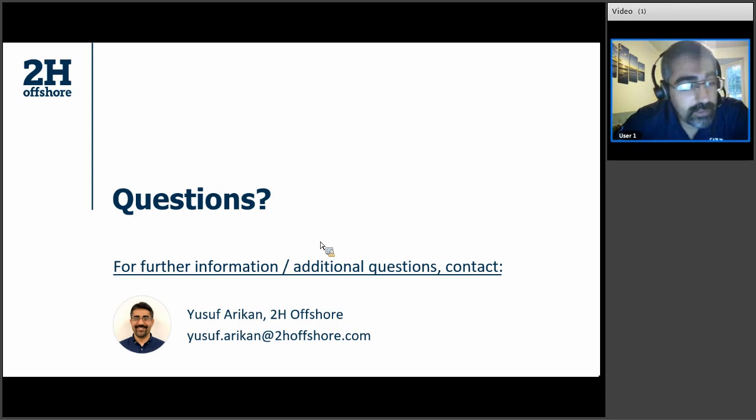Anchors, okay, that's a good question. I was saying we are eliminating the chain and we are looking at the taut configurations. One drawback of using taut configuration over the catenary configuration is the anchor type, because for a taut system, our anchor needs to have capacity to resist vertical loads, basically uplift force.